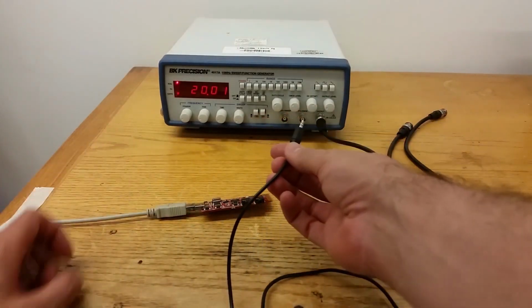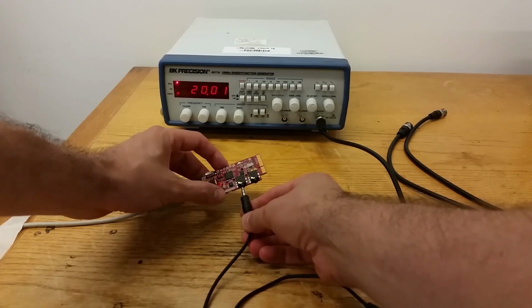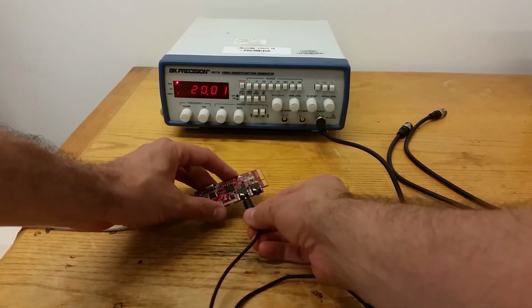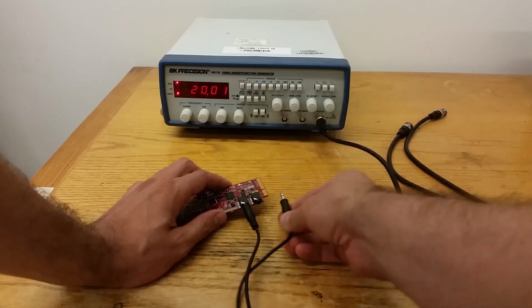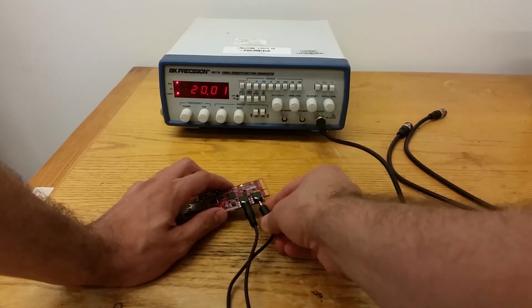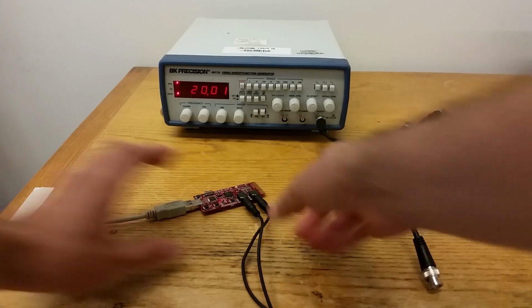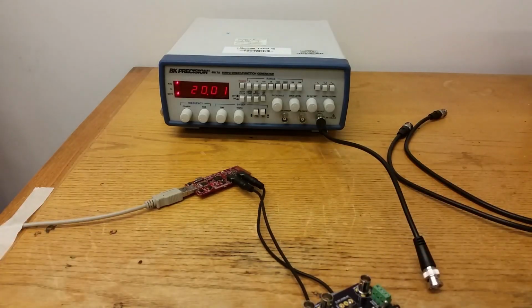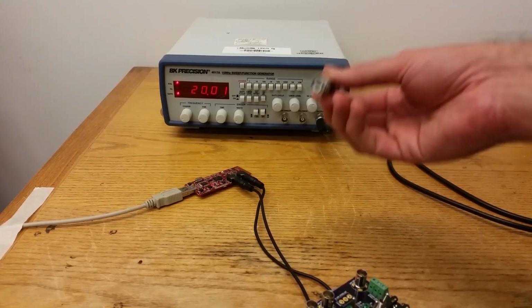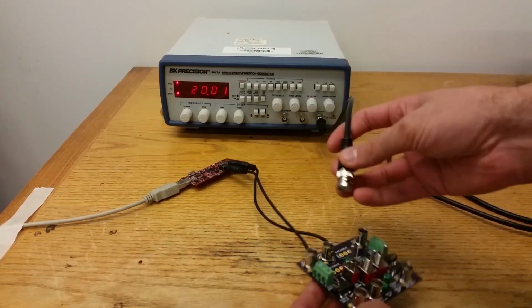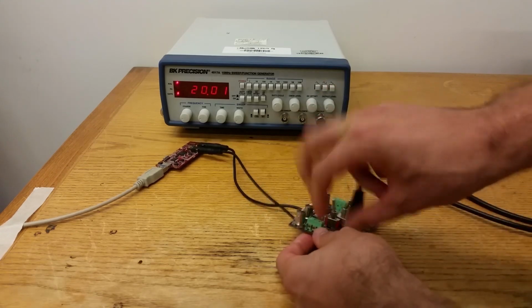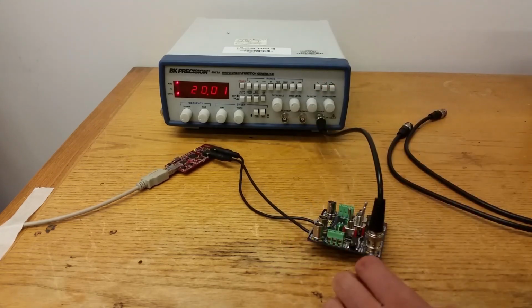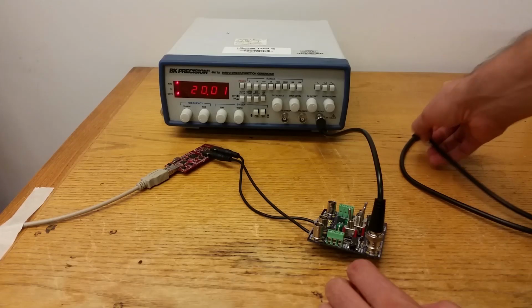I'll connect our audio input here to the jack labeled stereo in on the signal processing board, and then I'll connect the stereo out jack here to the one labeled HP out. And now I've got that board connected to the mixer, but I still need to get the signal into it. And we do that with this cable right here. This is connected to the input part of our board here. Screw it on tight, and then we'll connect up the oscilloscope as well.